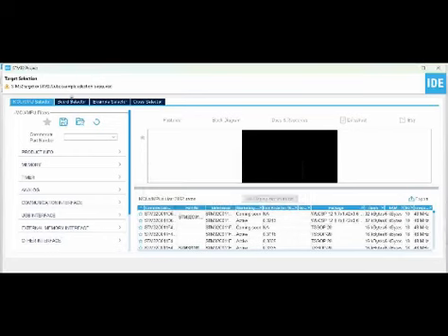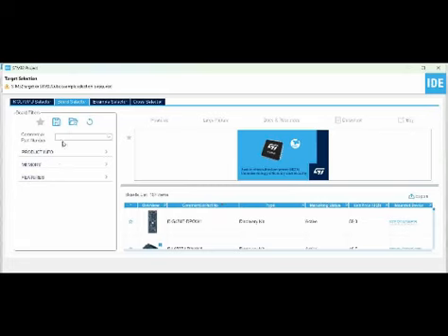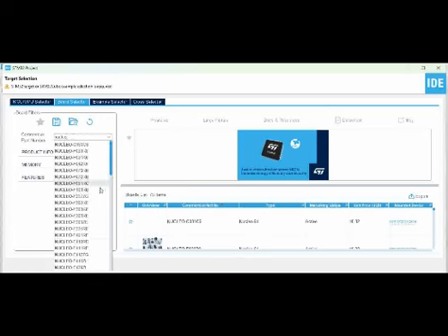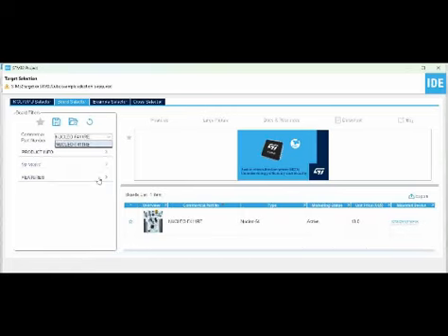Once the board selector tab opens up, go to the commercial part number section, click on it and type Nucleo. Once you type Nucleo, you see your board will get listed here, and you can click and it gets listed here.